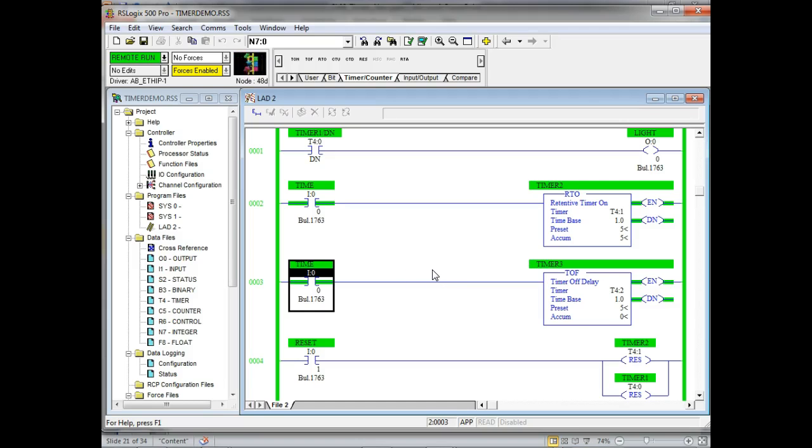Nothing happens, right? And it says it's done. It went to 0, right? Okay. And then when I turn it off or make the rung false, this is when it starts timing, which is what you would normally use, right? So an off delay timer, you would want something to be on until it times out, right? You understand that? Are we okay? Everybody okay?